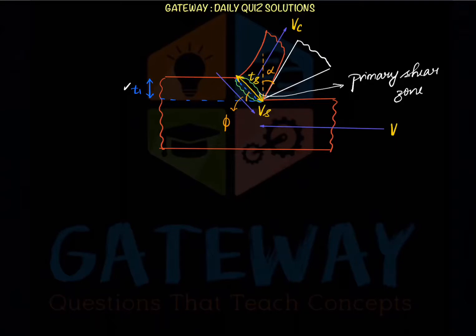In the primary shear zone itself, we spend 70 to 80% of our energy in cutting, to break the crystal structures. That is our major part here, the primary shear zone. And in the question it is given as the mean thickness of the primary shear zone. If we draw the primary shear zone separately here, this is our primary shear zone. It is a zone actually. Generally, for analysis purposes, it will be taken as a line.